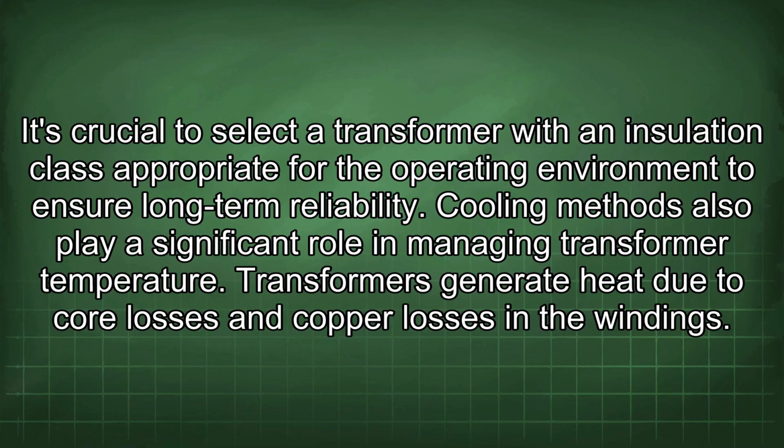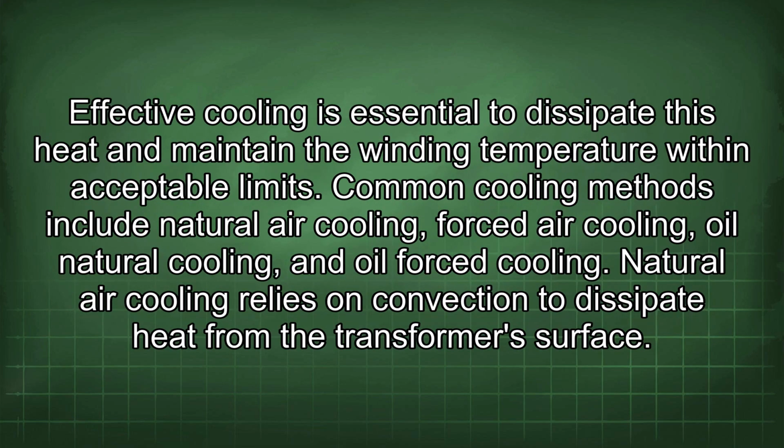Cooling methods also play a significant role in managing transformer temperature. Transformers generate heat due to core losses and copper losses in the windings. Effective cooling is essential to dissipate this heat and maintain the winding temperature within acceptable limits. Common cooling methods include natural air cooling, forced air cooling, oil natural cooling, and oil forced cooling.